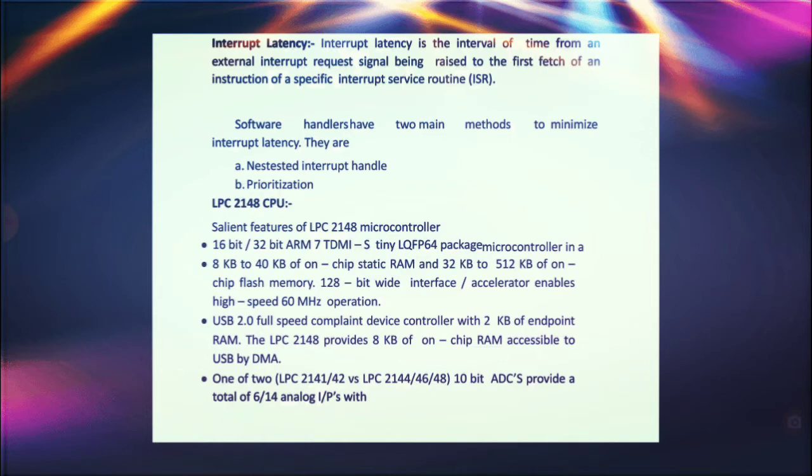It is a 32-bit ARM7TDMI tiny LQFP64 package microcontroller with 8 KB to 40 KB of on-chip static RAM and 32 KB to 512 KB of on-chip flash memory. 128-bit wide interface accelerator enables high-speed 60 MHz operation.